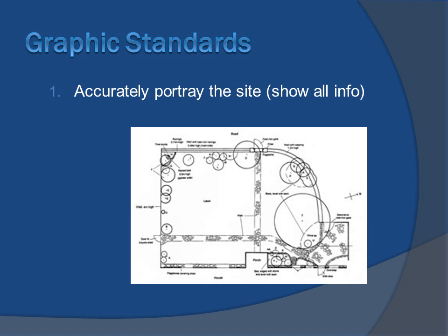We're going to accurately portray the site. We're going to show all information. And basically what are we doing there? We're getting a survey, blowing it up, and drawing it to scale. In Hort 112, you guys are already doing that. I give my students a copy of a survey from a surveyor. It's at 1 inch equals 50 scale. They're blowing it up to 1/8 scale and putting it all on paper. They're going to draw everything on the site: the sidewalks, the driveways, utility pole, heat and air conditioning boxes, the water meter where it's connected to, the sewer cleanouts.